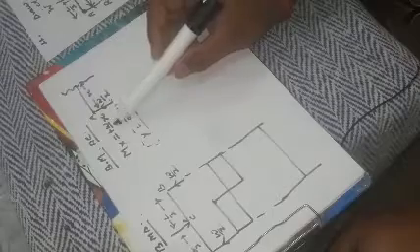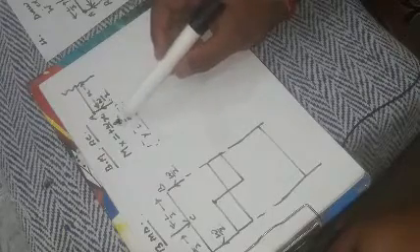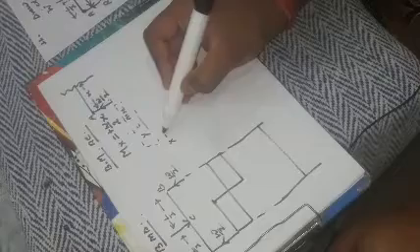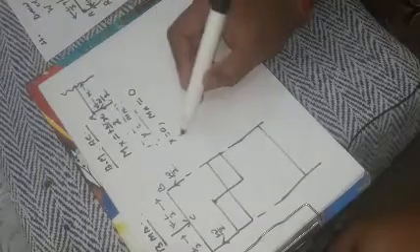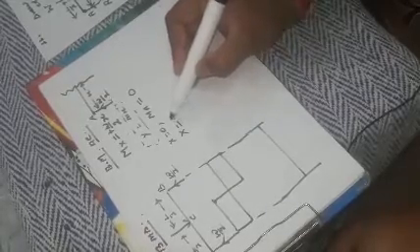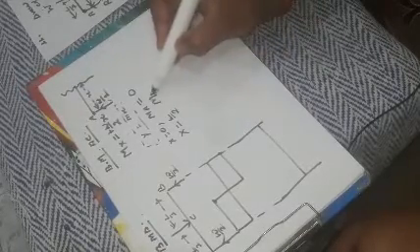Now we will calculate the bending moment value for each point covered in this section. So the covered points in this section are A and C. For x equal to 0, the point is A, and the bending moment value at point A is 0, and the second point is C, and for this point x equal to L by 2, and the bending moment value for this point is W by 2 into L by 2, WL by 4, right?